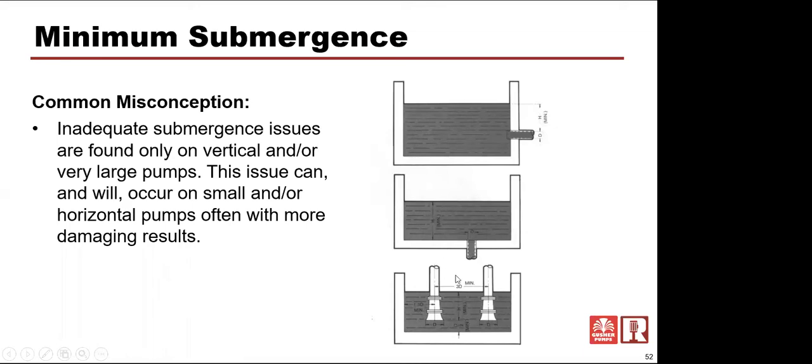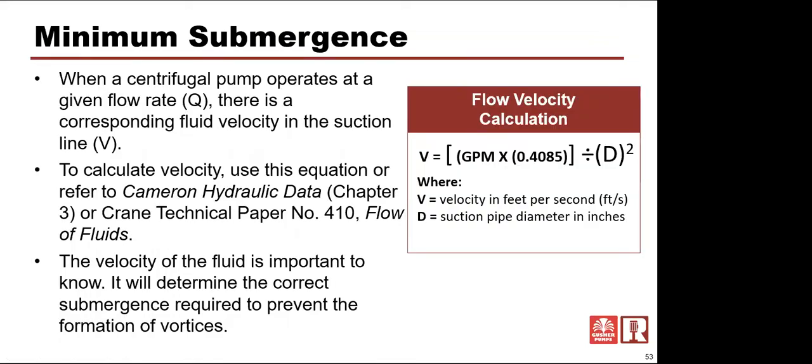Again, you want smooth laminar flow coming into a pump, whether it's a vertical or horizontal. So in this case, they're recommending at least 3 diameters of this pump intake between centers of these pumps, which are verticals, or between centers of suction pipes if they're horizontals. Again, we're trying to get nice, smooth, clean, consistent flow into that pump. The pump's going to be happiest when we have that. We want happy pumps.